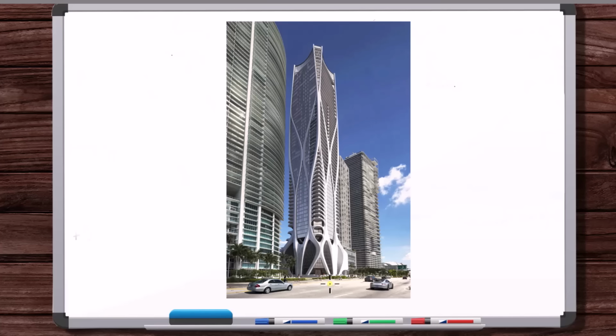Now, you wouldn't think about ground as earth in all circumstances. So let's say there was a floor here that had high ceilings, and then there was a machine shop on one of these floors, and there was a big pump or something in the machine shop, a big machine, a big drill. Well, ground in that case would just be the concrete floor in the machine shop. The concrete floor of the machine shop is infinitely stiff compared to the pump or the drill. Just like the earth is infinitely stiff compared to the skyscraper.